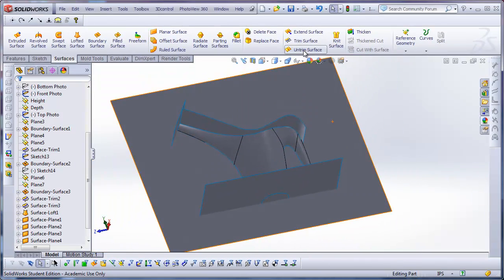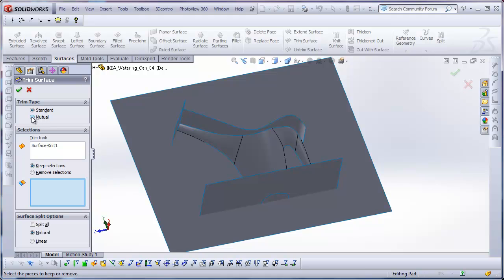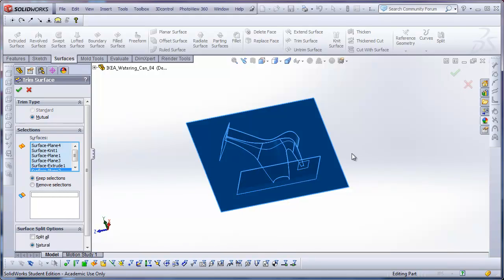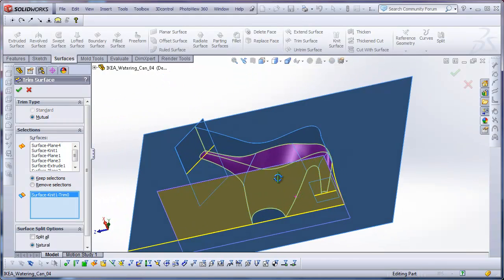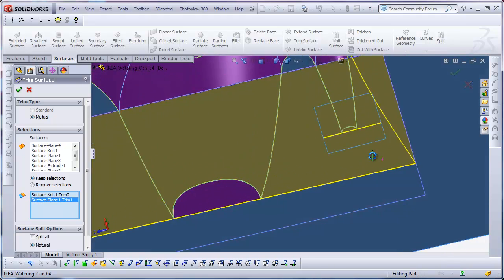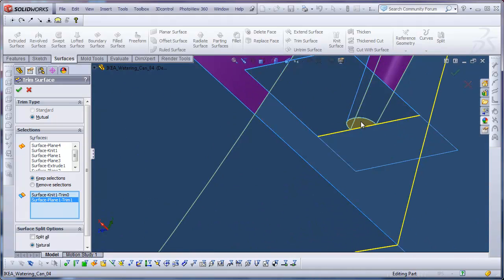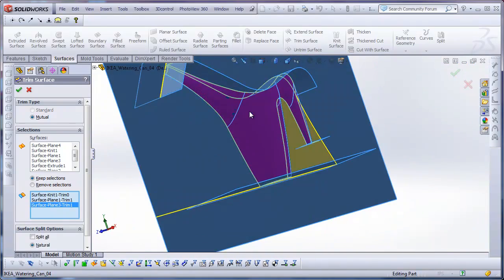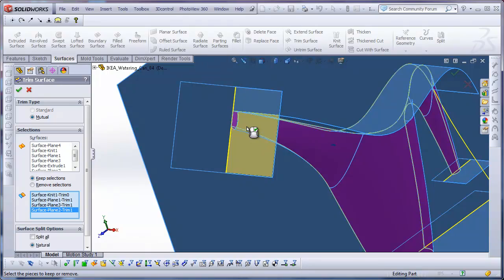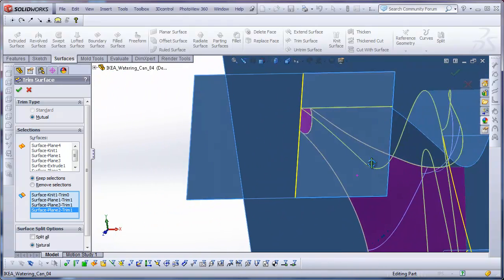And then you'll see when I do the mutual trim, click on mutual trim, I'll clear this for a second and draw a rectangle around it. It'll select everything. When I do a mutual trim, you'll see it treats it as one as opposed to four separate surfaces, which is a nice feature. And so I'll often do this if I have any pre-trimmed surfaces.